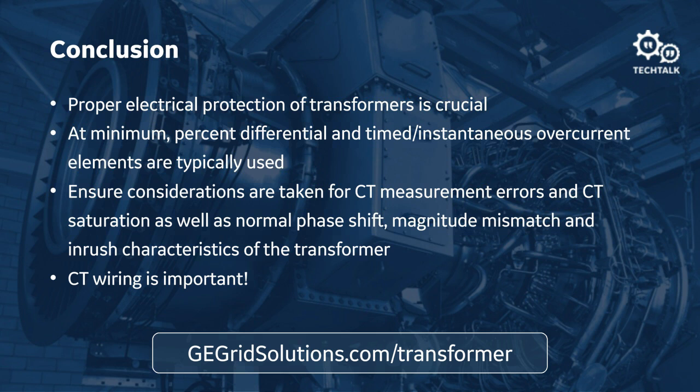All those relays have been replaced with a similar 8 series relay. So we have the 869, the 889, the 850, and the 845. They're the same cutout. Settings can be converted, basically the same functions. If you're affected by this, let us know and we can provide more info to you on how to ease the upgrade process or even come in and show you the new relays to you.